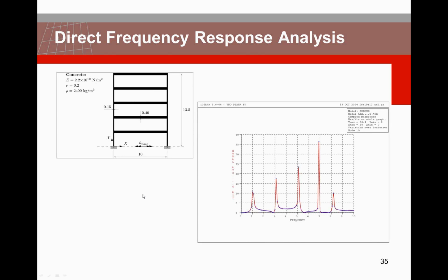Results, as for the modal frequency analysis, will be presented in the frequency domain as, in this case, a nodal acceleration, and here you see the typical spikes coming back at the eigenfrequencies for this 5-story building.